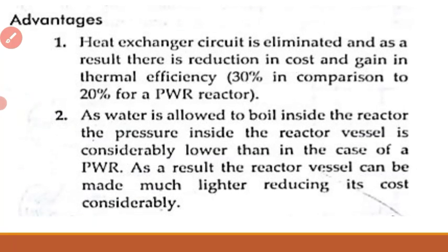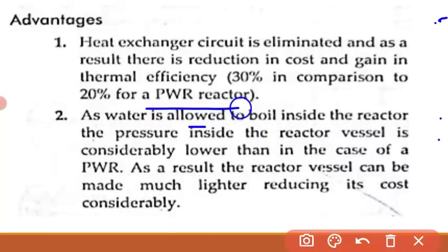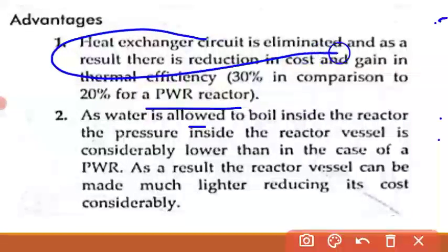will be reduced in comparison to the PWR. I will explain the PWR, the pressurized water reactor, later. Here the heat exchanger circuit is eliminated, hence the cost will be less. So what does it achieve here? The thermal efficiency will be 30% more as compared to the PWR.